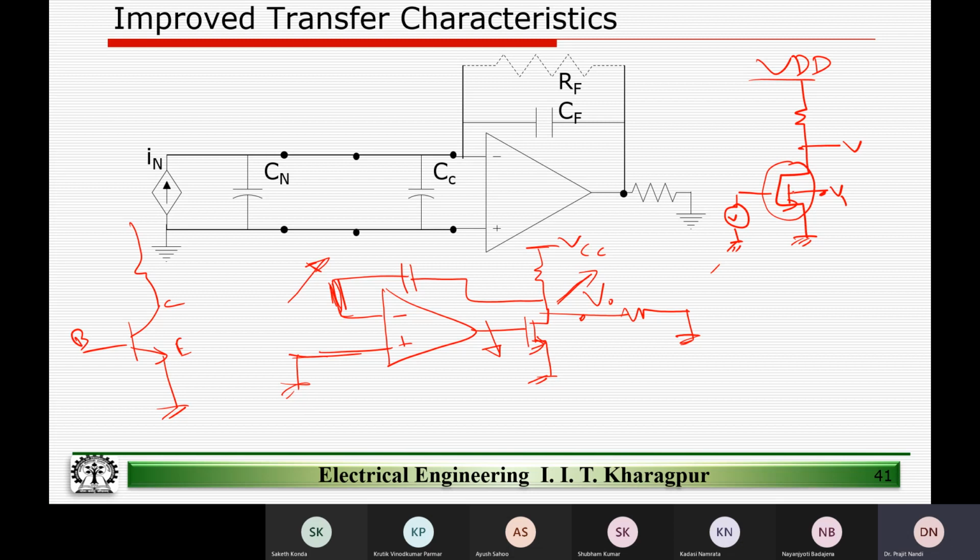This is what I can do. So you need to have a control on the voltage. You need not always rely on the device guy, which in this case is Shubham, to be able to tweak the threshold voltage, right? So in many applications, you will see the body or the bulk. So there are many names for the body. Sometimes we call it substrate, sometimes backgate, sometimes bulk or body or whatever. But substrate is actually misleading. So we'll talk about this.